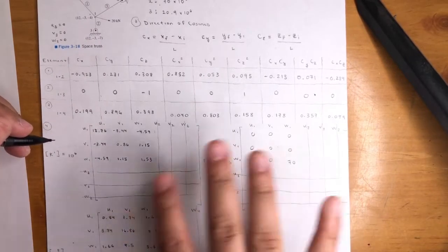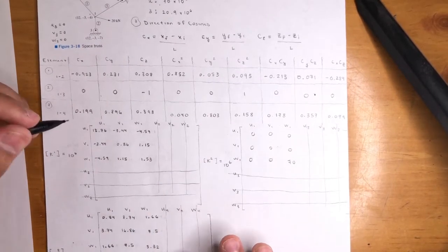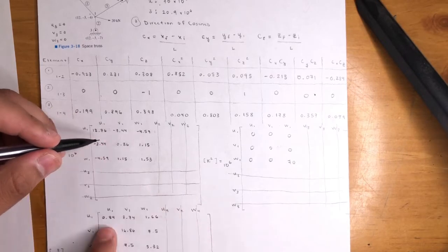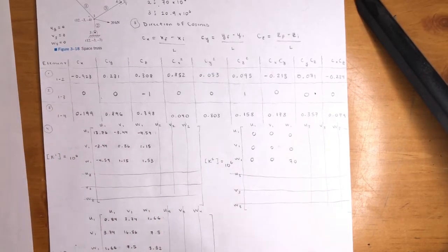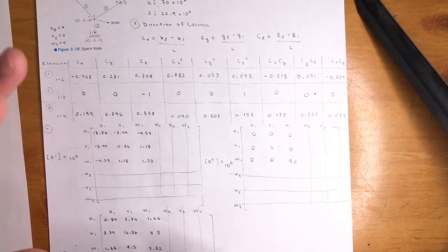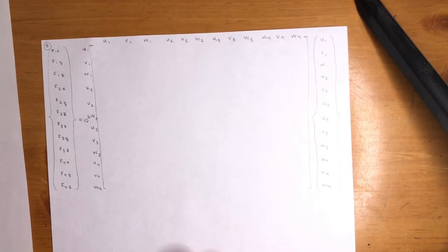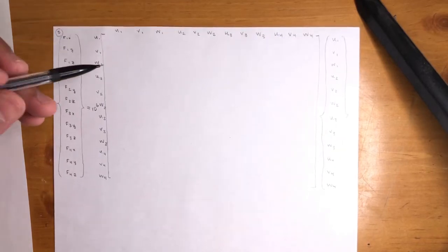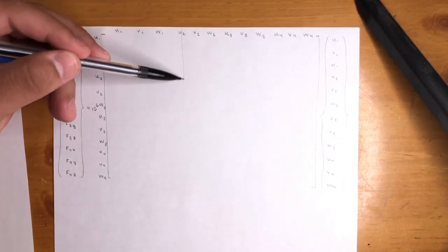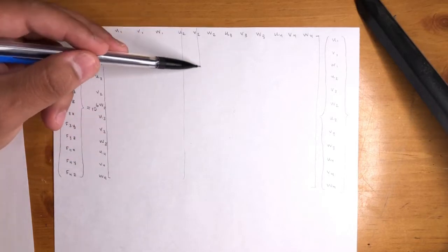So that means I could go ahead and add these matrices together, right? All the U1s, that one, this one, and that one, and come up with another 3x3 matrix. It's called your global stiffness matrix. So let's go ahead and do that. I already have it pre-written here, but same thing here, right? I'm gonna go ahead and apply the boundary conditions. So all this gets canceled out.